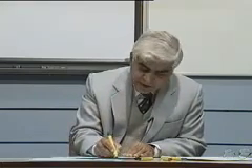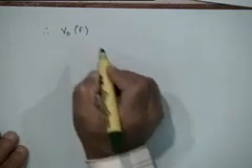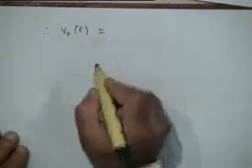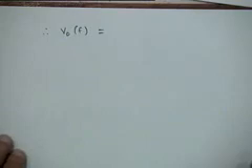So if I have that low pass filter, now if I look at the output of the low pass filter in the demodulator, what will I see? So therefore V naught of F, that is the output of the low pass filter, which terms will you see? The first two terms, right?